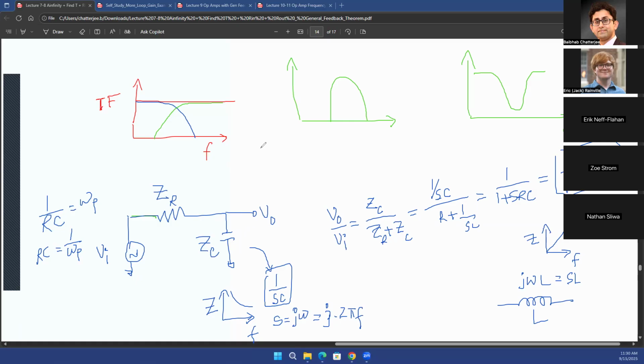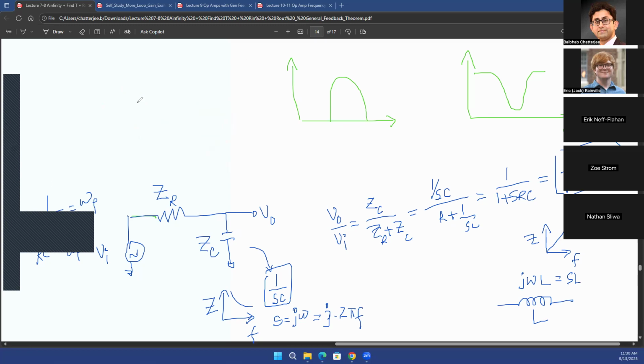Now, also, why do we call it a low-pass filter versus a high-pass filter? First, you may take a look at a frequency of 0. If you take omega equal to 0, your denominator will become 1 plus 0, which is equal to 1. Your numerator is already 1. So you have a factor of 1 at 0 frequency.